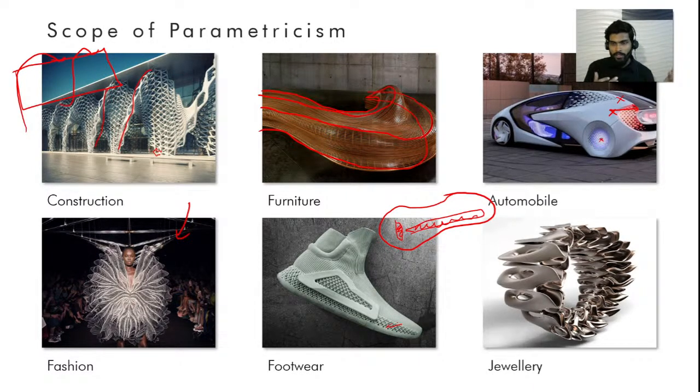So instead of printing with the same material, they realized that when the pressure is exerted the most here, why not use some hard material here, or a higher compressive strength material here, and in the other areas we can make the meshes a bit less dense, and it could reduce the entire weight. So as you can see, some of the meshes are relaxed and some of them are very tightly packed. So that is how they brought in this revolution.